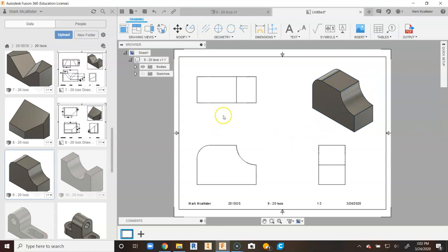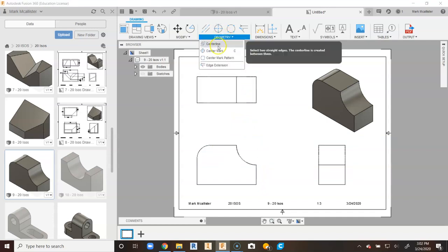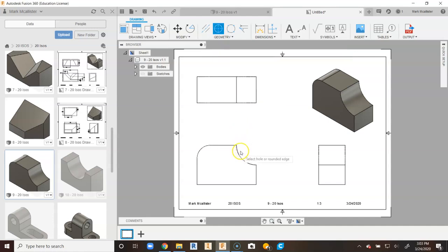So we have a new line type to place because we have for ourselves this radial cutout of our object, and we also have a fillet off of the side. So we're going to come up to our geometry tab, and we want to find a center mark. When we click on center mark, we want to come down and click on the arc radius here of the object, and that's going to give us a center point of that arc. And we're going to do the exact same thing with our fillet, and it's going to give us a center point. So like I said, this is a radial arc. It has to have a center point to be drawn from. It's going to give us those center points from those lines. I'm going to right click and I'm going to say OK.